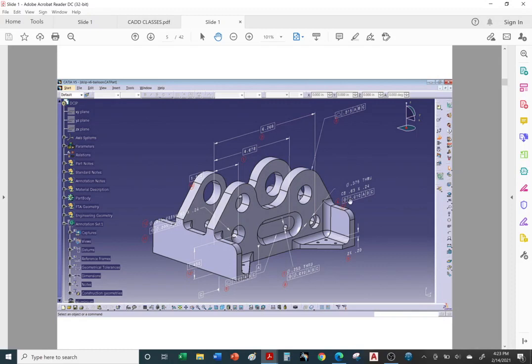Here's another frame, has a circle and a crosshair inside. That's telling the machinist, hey, the axis of this counterbore hole can only be off by 10 thou in any direction radially. So again, the thickness of a hair is 5 thou, 0.005. So where you need precision, you want to tighten it up. You can call it out in your GD&T, and then you have ABC. That's your axis. That's your XYZ axis for inspection and for machining, except we call it out with ABC.